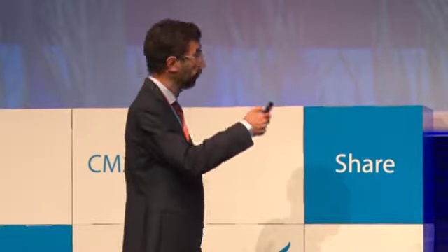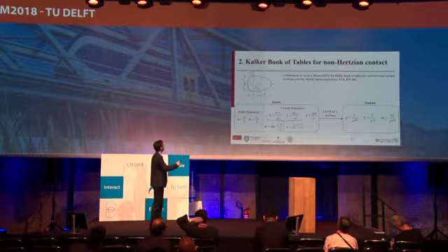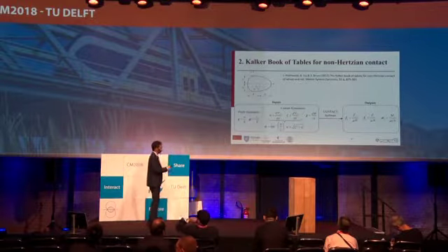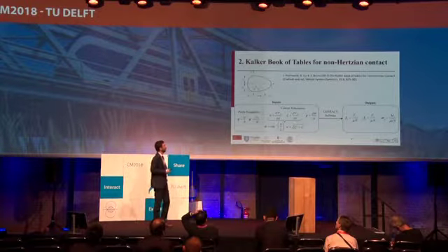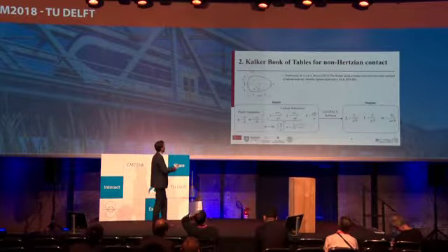It is made up of two half ellipses, one in the negative values of y and one in the positive values of y, so that, of course, just some of the possible non-Hertzian shapes can be well reproduced. And this requires, compared to the elliptic contact patch, one additional parameter, which is this y0, which can be turned into a non-dimensional shape factor psi, in addition to the usual A over B semi-axis ratio, which is typical for elliptic contacts.